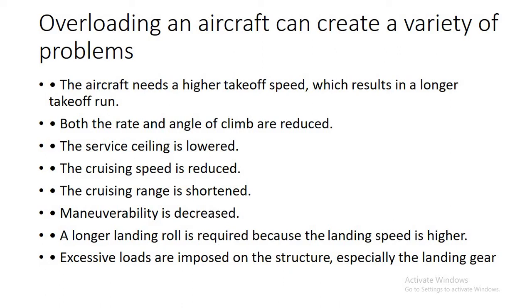If your weight is more, then you have to speed aircraft at a higher speed to take off. It means your takeoff run will get longer. Number two, your rate and angle of climb will be reduced. Earlier aircraft was climbing at a faster rate. When your weight is more, your rate of climb and angle of climb will slowly decrease. Then your service ceiling will be lower. Service ceiling is the maximum height that you can reach. Your aircraft will not reach as high as it used to be in the earlier stage.